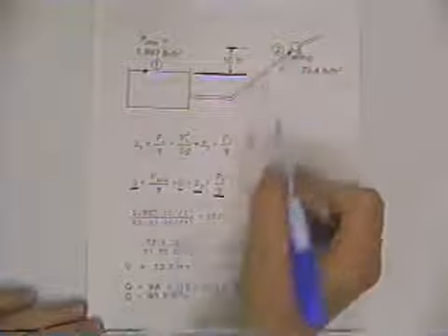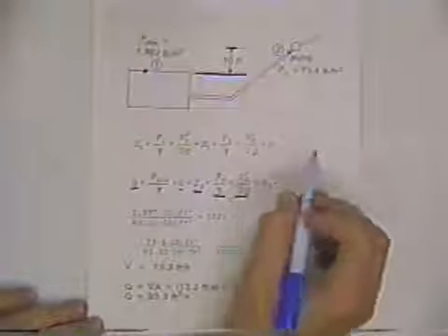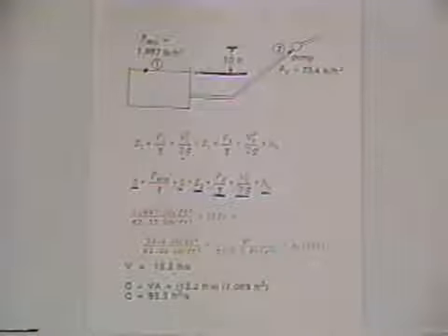And again, the reason we're doing that is because we're recognizing the physical situation that we don't want vaporization to occur. So that's part of the statement of the problem. And then there will be a very definite velocity of flow here, and that's the velocity head. And we've got a head loss, which the Darcy-Weisbach equation is going to take care of for us.